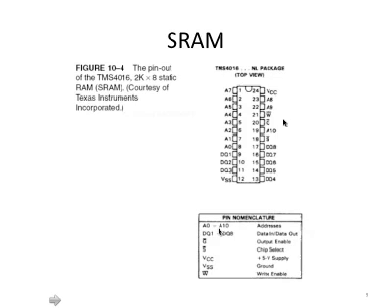Also, as part of the datasheet for this chip, you will see these explanations of these signals. Output enable, chip select, write enable. The symbol used for each chip may be slightly different, but they all have to have these functions: chip select, write enable, output enable, in addition to the power and ground.